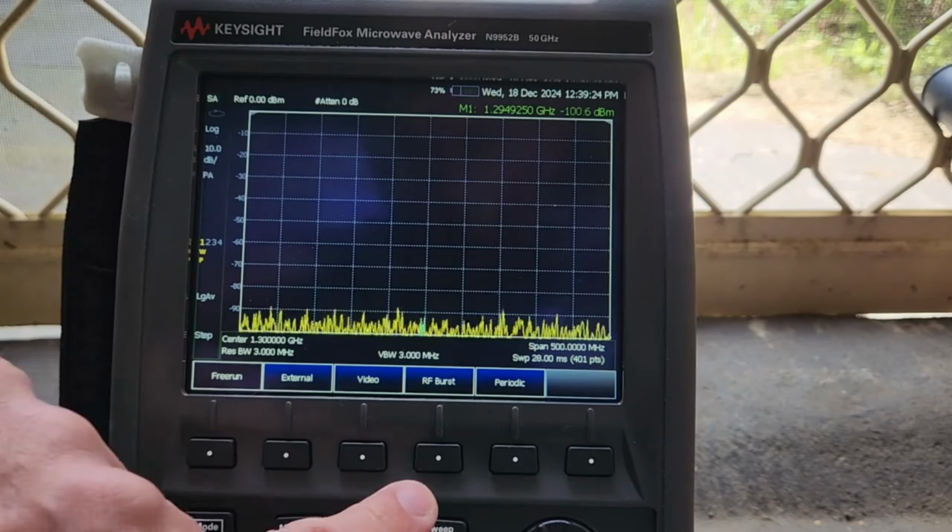So the next thing I want to do is to turn on the trigger. Okay, how do I change that? So we change the sweep type to FFT instead of step. Then trigger video, it's about -60. Maybe a bit lower. I'll turn it on right now.